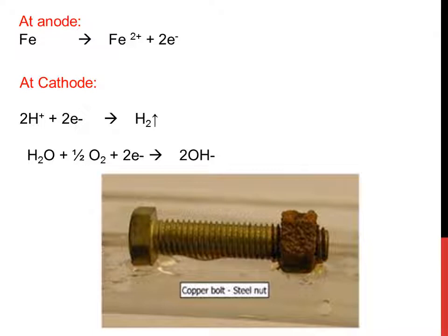And also we can apply coatings, like painting the cathodic area or both the regions, and keep the coatings in good condition. And also while designing we can avoid threaded joints for materials far apart in the galvanic series. So this is how we can prevent galvanic corrosion effectively by various ideas.